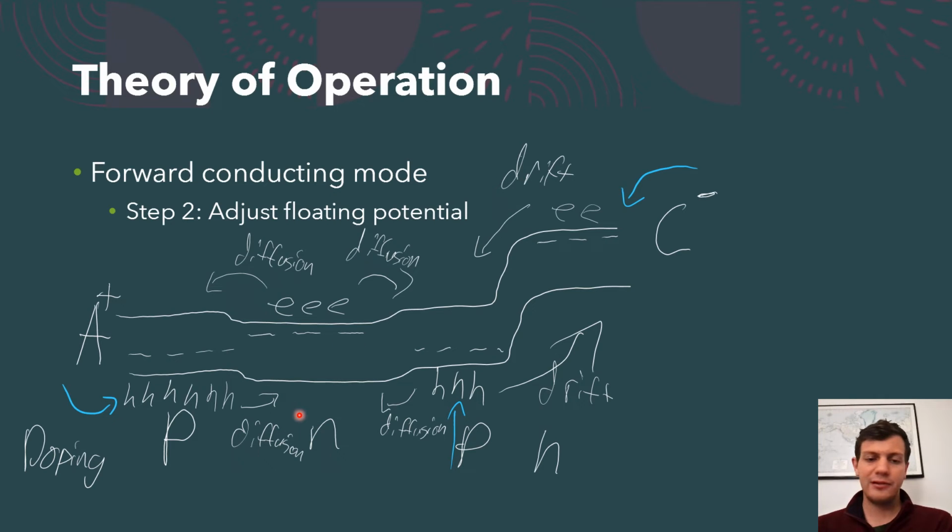level at a constant level or anything. It's just going to start rising as electrons diffuse out of the device and holes diffuse into the device. It has no reason to replenish these electrons that are up here. Nothing is going to keep it up at that, or nothing's going to hold it down at that high voltage. So all the holes are being provided from the anode and electrons from the cathode over here.